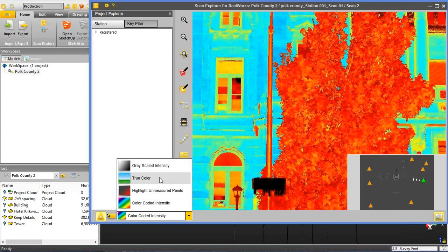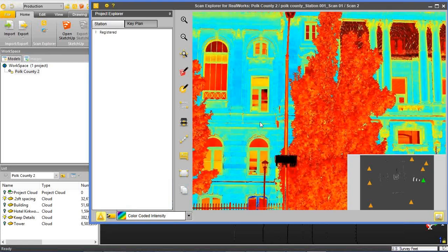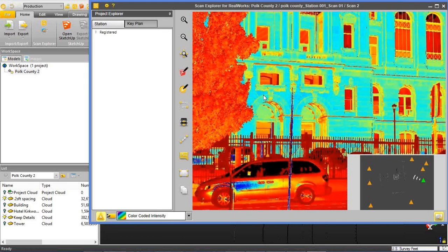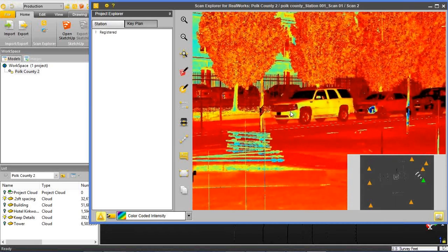Imagery is good for taking measurements if you've got color behind it. However, if you're around a corridor or a busy sidewalk or an active job site, your scan happens first and your pictures are taken after. That means cars are moving, people are walking by, and somebody could move a piece of equipment in front of you.